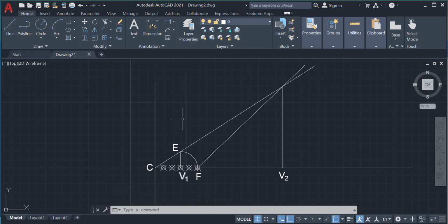Okay. So now I will take an offset of this line. At how much gap? 10 mm, 15 mm, your wish. So just click on this line. Click on this offset option. As soon as we go for offset option, it is asking me the offset distance, how much you want. So I'm taking it as 50 to save the time. But minimum you should take 10.